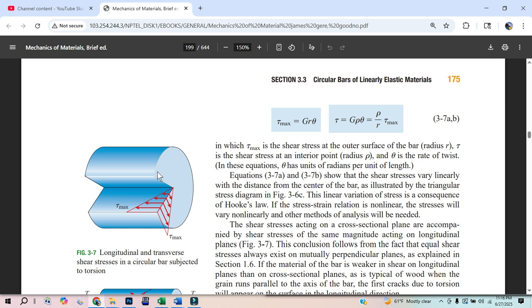But you'd have to actually divvy this cylinder up into rings and then say, hey, if I have a ring of area, like let's just do this ring right here, and then just that outer portion. Cool, that's the material, but you can see some of that material is at the full radius, and the other is just slightly over here.